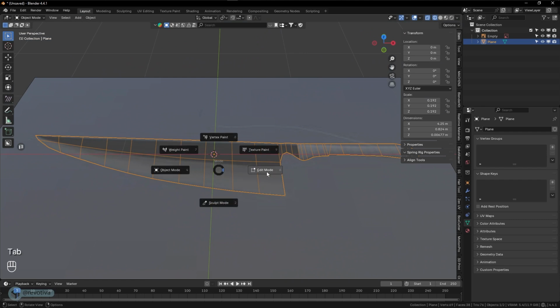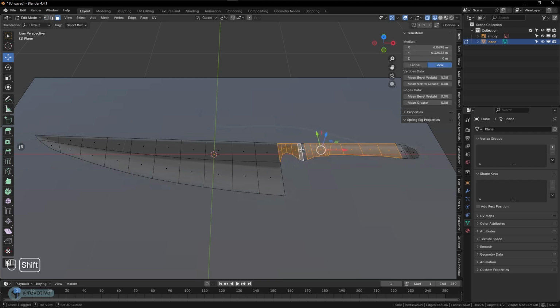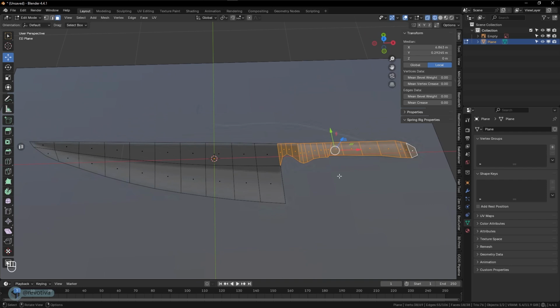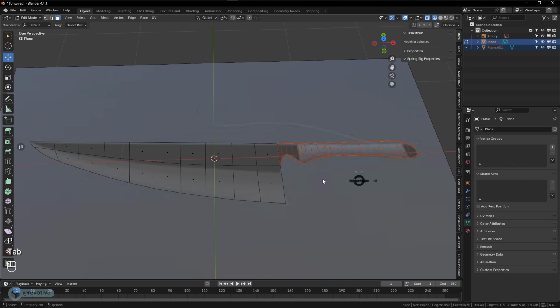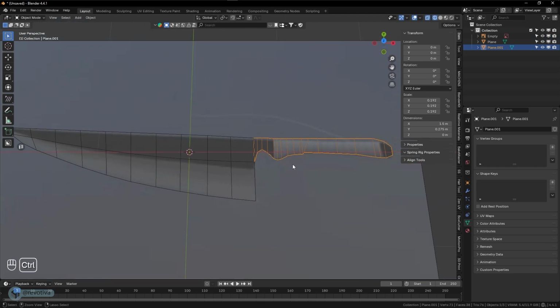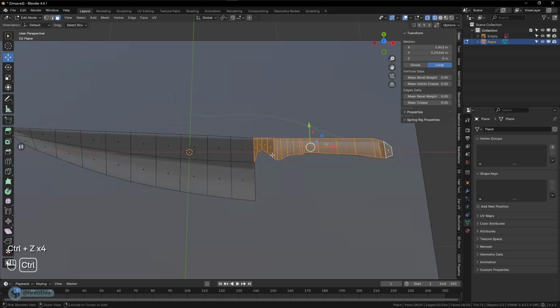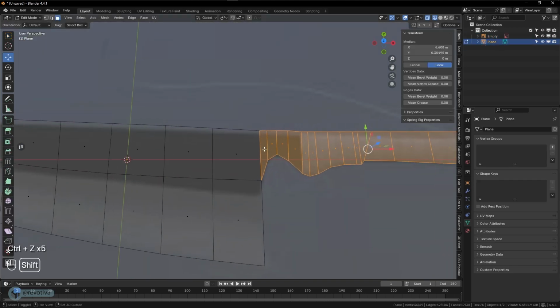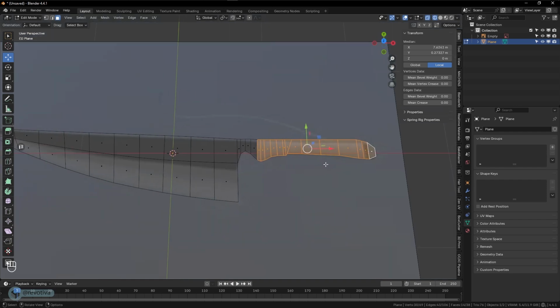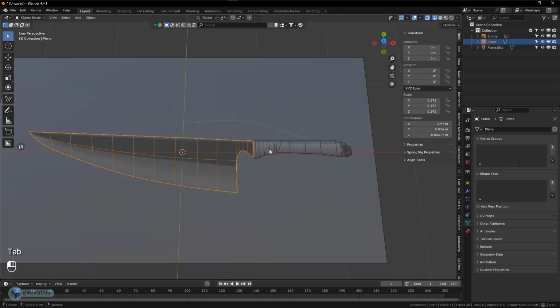So there you go. I will come to edit mode, select face selection, and I will select these faces. I will press P, separate by selection, and so I got these two pieces. I have to deselect this part because this is iron. So right now we press P, separate by selection. I got the knife and the handle.